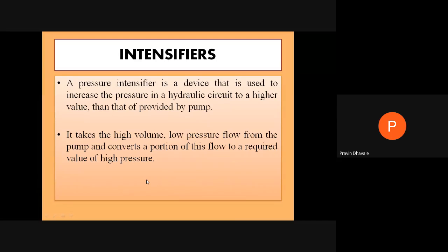Whatever fluid is supplied by the pump, high volume, low pressure, some portion of that flow will be converted into high pressure by using this intensifier.